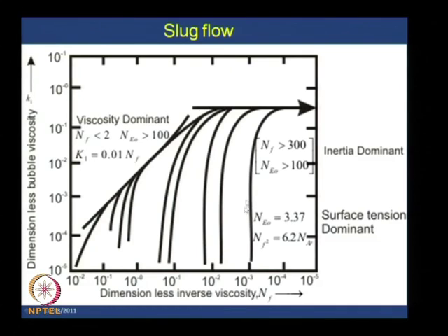parameter. So, from this particular case, if we know the Archimedes number, you can locate the particular curve, you know the dimensionless viscosity number, you locate the point, and from there, from the y axis, you can find out the dimensionless bubble velocity, which is nothing but the Froude number. Once you can find out the Froude number, you can find out the u infinity as well.